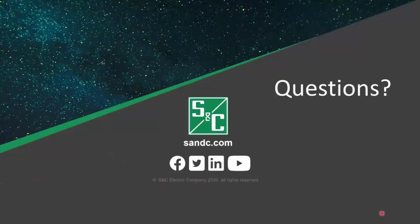The first question was from Lionel. With present-day numerical relays used on medium voltage and electronic protection on low-voltage breakers, can we still stick to Table 15-3 in the Buff Book? Is that a question through a transformer? Yeah, from medium voltage to low voltage.